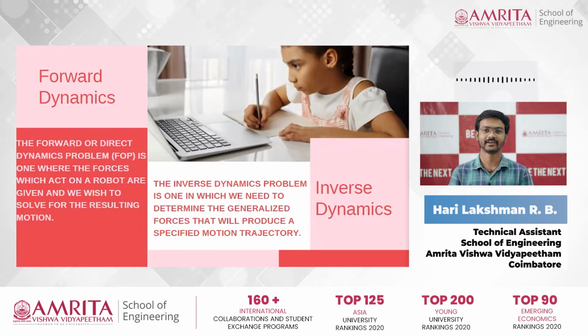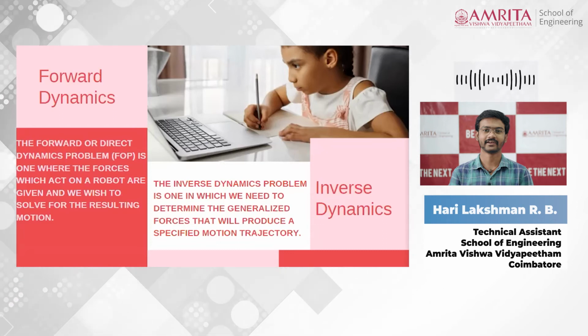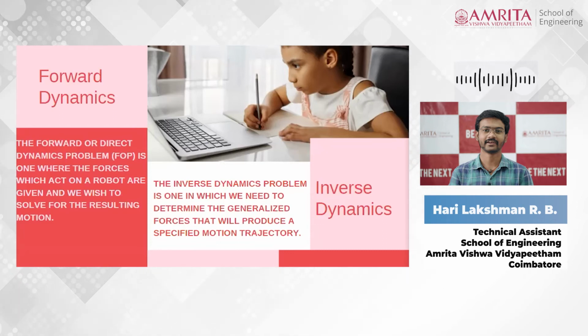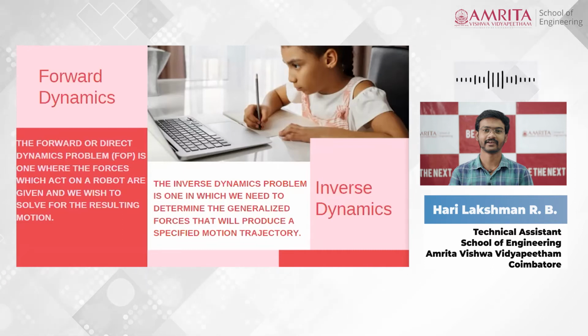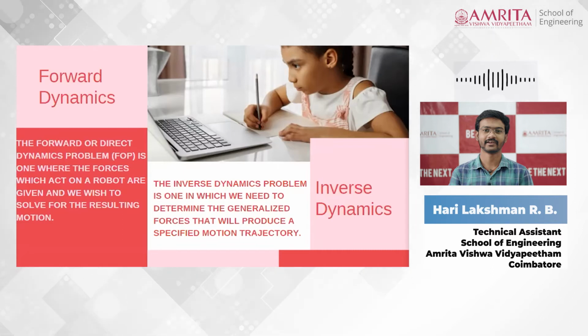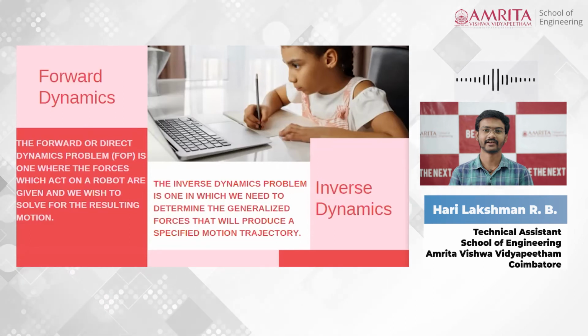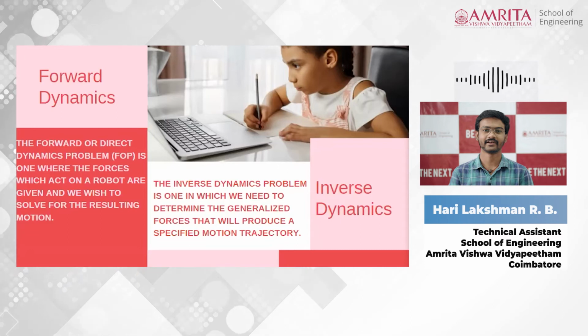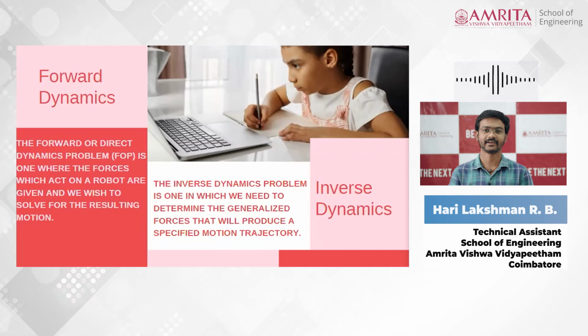Moreover, to ensure convergence of the control scheme, the inverse dynamics computations may have to be performed very frequently. Consequently, the formulation and the evaluation of these equations of motion affect the servo rate of the robot controller and partially determine the feasibility of implementing many controller schemes online. So basically, inverse dynamics is nothing but giving a motion and determining how much force would be needed to achieve that motion specifically.